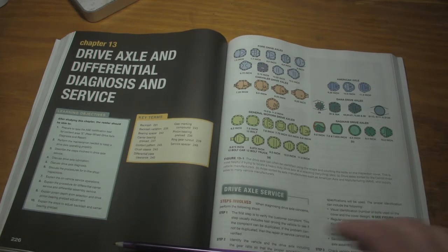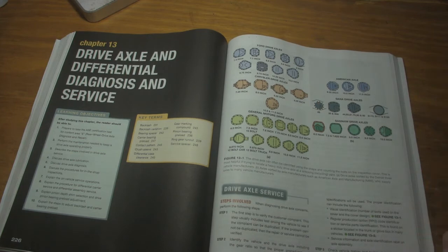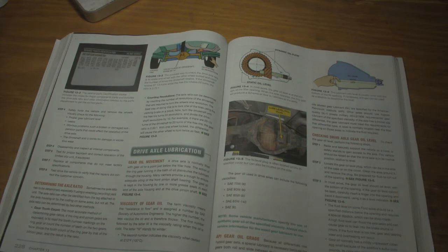One of the ways we're going to do that is by referencing service information, which is my favorite way to do it. Service information is going to allow us to look the vehicle up by VIN number. And the VIN number, hopefully in most cases, will identify the RPO code. The RPO code is going to list what the manufacturer put on that vehicle from the factory. So if we are trying to figure out what the differential is and we're not quite sure, we can reference service information. If service information directs us to an RPO code, we can go find this tag either in the glove box, door jamb, something like that.